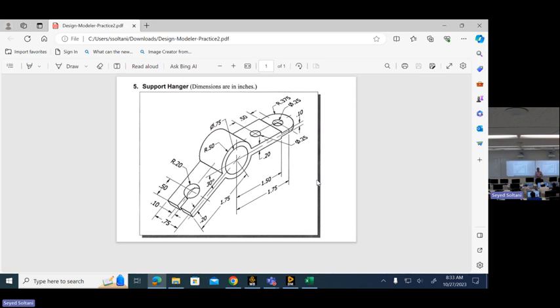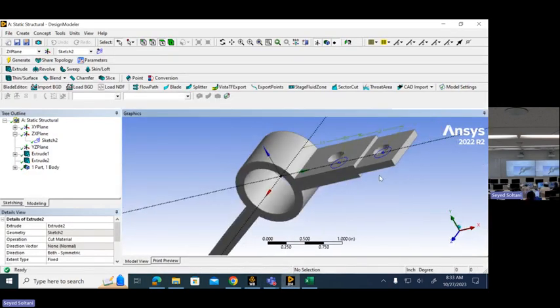The only thing it needs is specifying the edge where you want to add the radius. So we're essentially using 0.375 as the radius. We're taking these two edges, this edge and the other one, as the places where we need to create that.